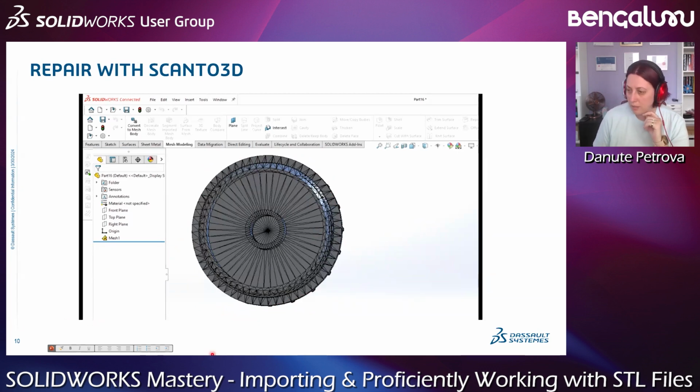But when you're starting, let me see if I can restart this one. At the beginning, it shows when your mesh has errors. So when you see that your mesh has errors, and it asks the question, do you want to reduce the facets? Just move it a little bit, slightly. In this case, it will rebuild the model and detect the errors. When it rebuilds the model and detects the errors, on the next steps it will automatically fix these errors. If you don't change anything, it will not fix your model.